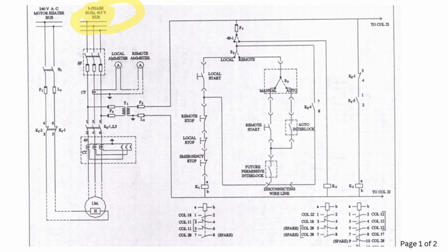a moist environment. To prevent moisture build-up in the motor, I mean in the stator winding, because it's normally hygroscopic in nature, a space heater with a 230-volt AC single phase supply is necessary to be kept on while the motor is in off condition, to keep the winding warm.